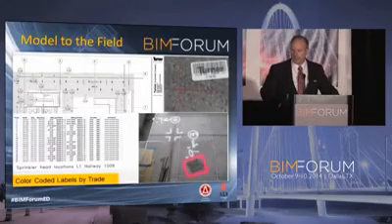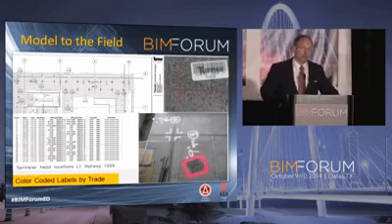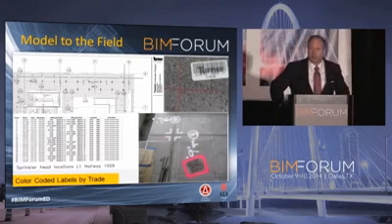The other part, too, of tying the model to the field, we do have to get back to fundamentals. Again, back to the X, Y, and Z coordinates. The interesting part about layout is once you start speeding it up, once you don't have to type in the X, Y coordinates for those targets in your HP42S anymore, and you click on them and you go from point to point, that labeling becomes the slowest thing out there. In this particular case, we had to speed things up. You've got to have a clean floor. It's got to be dry, and you've got to have a label.